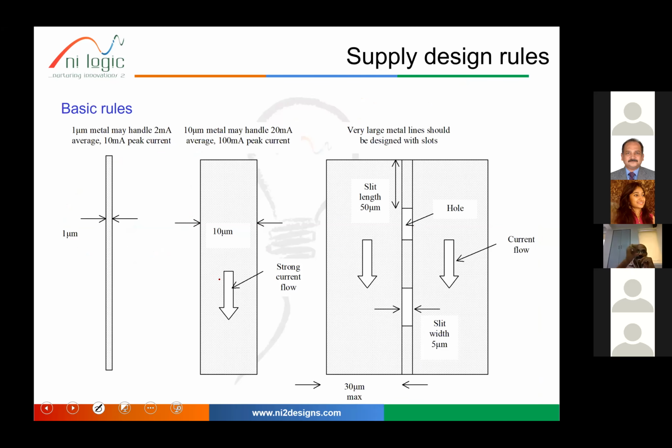So if someone makes a thin track carrying that amount of current, okay, so you can imagine what may happen. It will burn off. It will burn off very easily. So it's better to have a thicker track, knowing the amount of current that track is carrying. Okay, and at the same time, you also have to take care of the thermal effects on the chipset, because if that track is carrying the current for a long period of time, what will happen? It'll heat up, and a natural heat dissipation method should be designed.